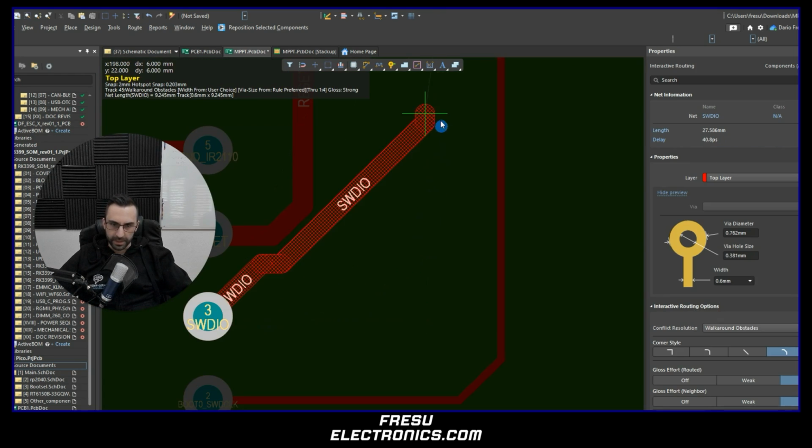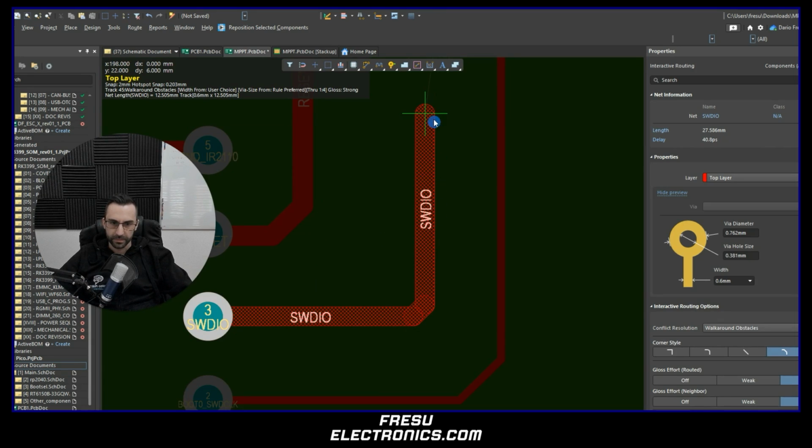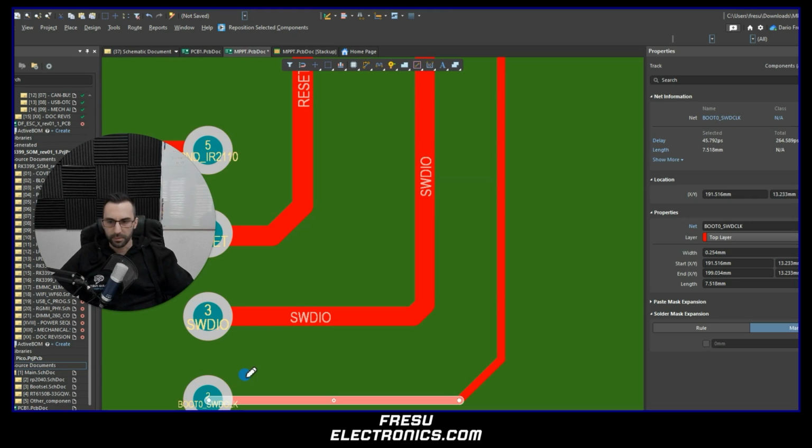But it's also important because it means that we have to be careful about what we put next to it. So what happens when we place in here another signal next to it, and the signal now is a low frequency signal? The return signal of this trace in here will try to cut corners to flow back to the source. And then this signal in here will also see this return current under its return plane. And this is what we call the ground bounce. So the ground bounce is basically a crosstalk phenomenon, and this is what causes the signal integrity issues in our electronic circuit.